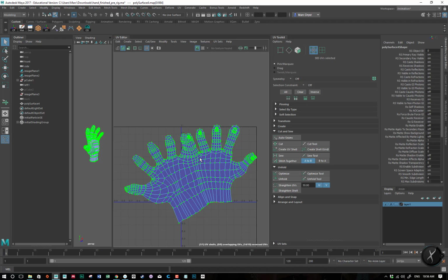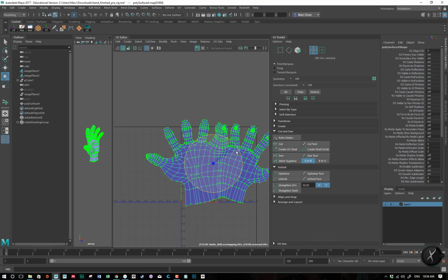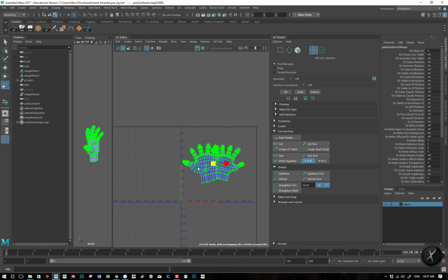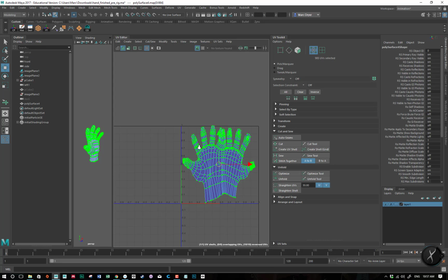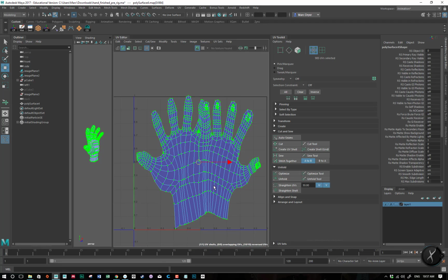But then the last thing to do, whatever your UVs are, is they have to fit within the 0 to 1 UV space. So I'm going to rotate and scale them down. Now you want to sort of maximize occupation of this space. Again, you don't really want to deform them too much, but I might want to stretch these up a little bit. And you have to avoid things like this, even parts where it's just going over the edge, because ZBrush or Mudbox will not accept these.